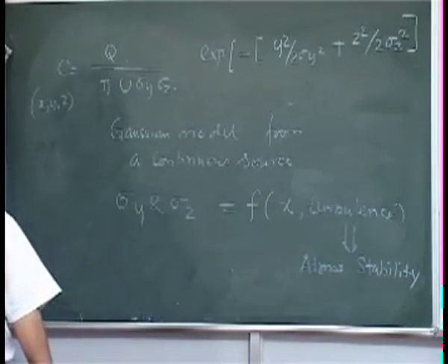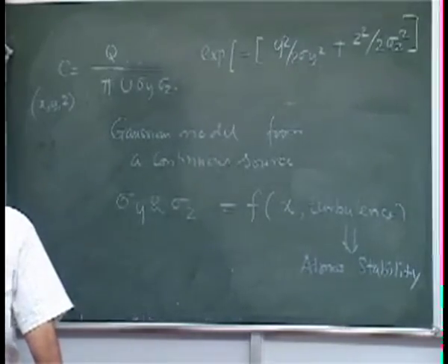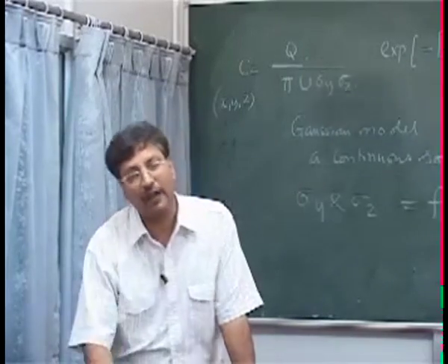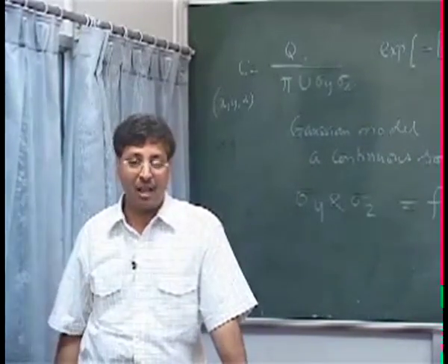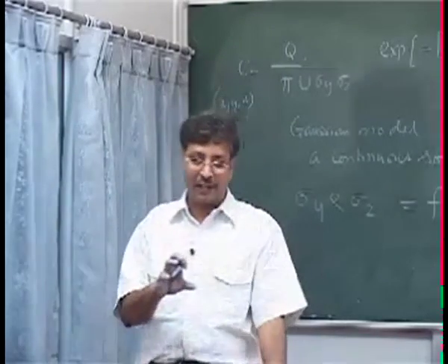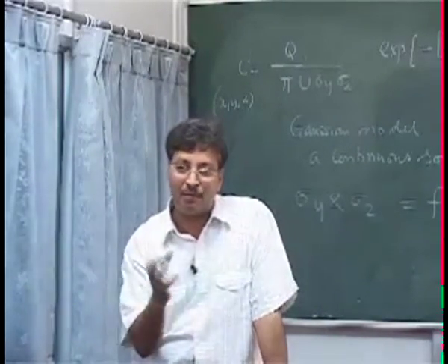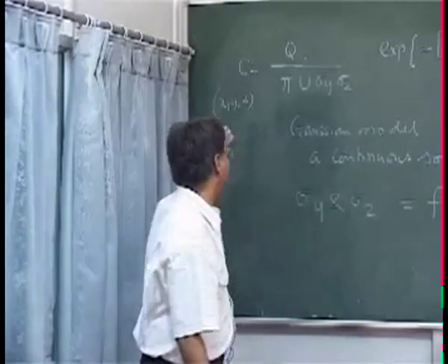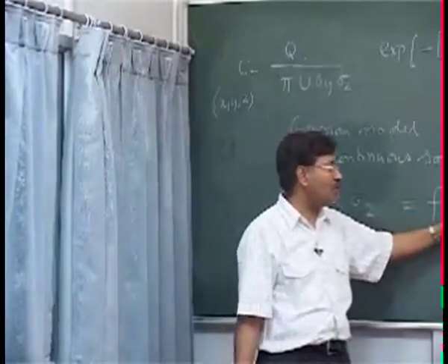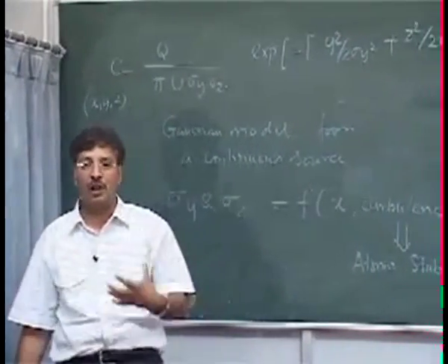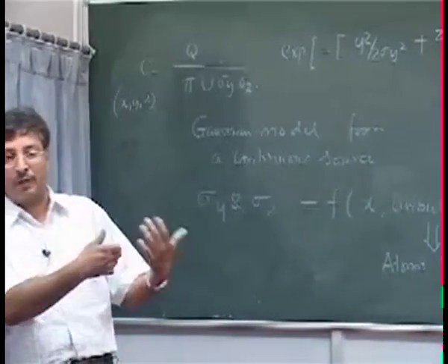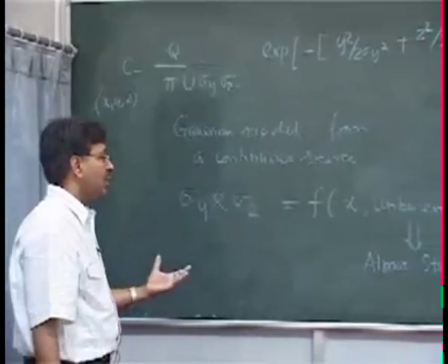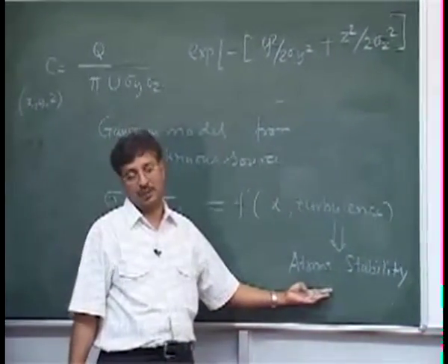If there is any question, I would like to answer. So the turbulence that we are taking, it incorporates both mechanical turbulence and thermal turbulence? Everything. Sir, how do we separate that? Either we need to separate that, or we somehow find a composite way to find that, because ultimately we want to find out the C. How to find that turbulence, which is mechanical, thermal, or because of the kinetics and things like that, we'll see, but by and large that will be governed by the atmospheric stability.